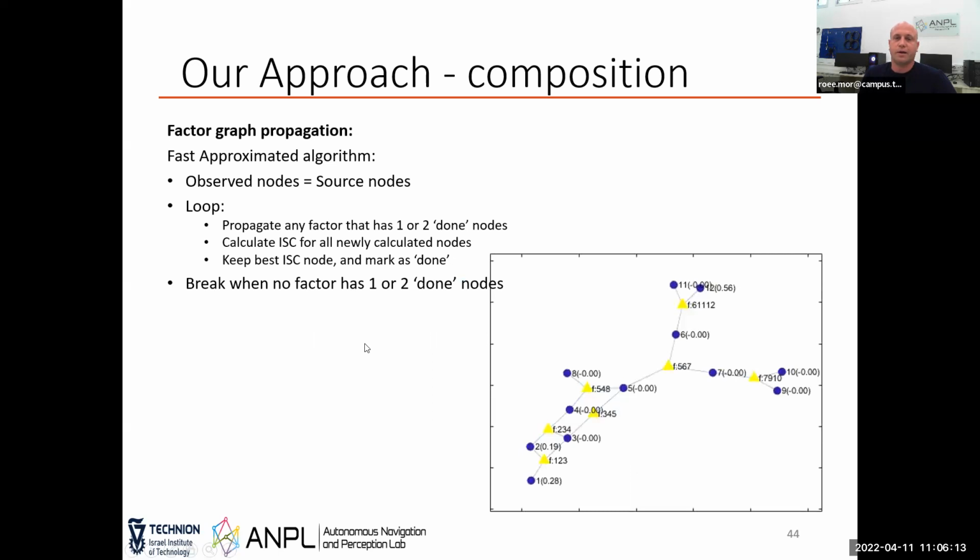So here is an example of how this algorithm works. In this simulation, we have 3 landmarks, 3 triplets with information. Okay, we saw them with the camera. We have inference about their state. And then at each step, we try to propagate data through the factors. For these 2 factors, we saw that the propagation is less informative. They get a lesser information score. So we took just the one that was most informative and forgot about the others.